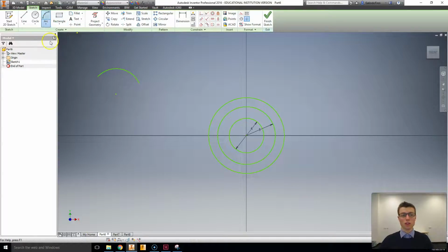The second option is the arc tangent tool. This creates another arc stemming from an existing line at a tangent to the original line. So, by selecting a point here, you can see how an arc tangent line can be created. And this can be used in a myriad of ways, not just from existing arcs but also from lines.